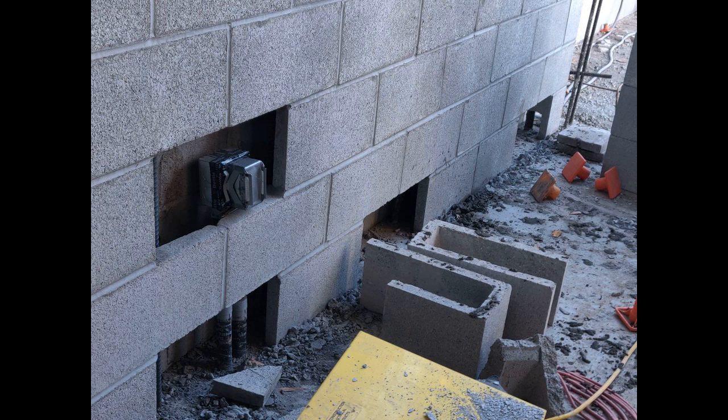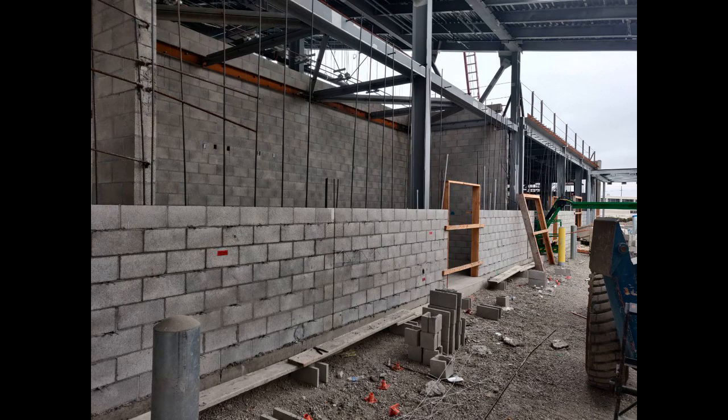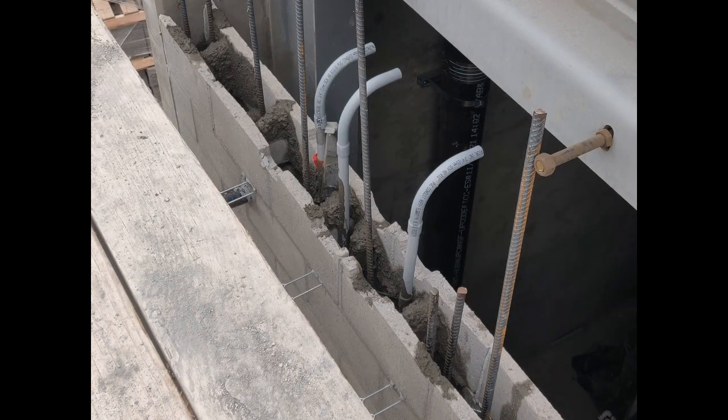Do not close cleanout holes until masonry work, reinforcement, and final cleaning of the grout spaces have been completed and inspected. For walls which will be exposed to view, close cleanout holes in an approved manner to match surrounding masonry. Grout placement. A grout pour is the total height of masonry to be grouted prior to erection of additional masonry. A grout lift is an increment of grout placement within a grout pour. A grout pour is filled by one or more lifts of grout.